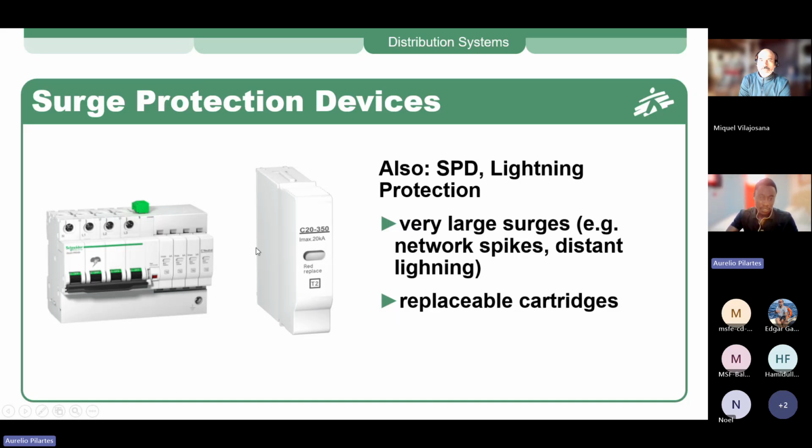In all installations, it's always a good idea to have some cartridges as spare, because during maintenance and whenever there is a surge and one of the cartridges is out, you should always have a spare easily reachable to replace in your SPDs.